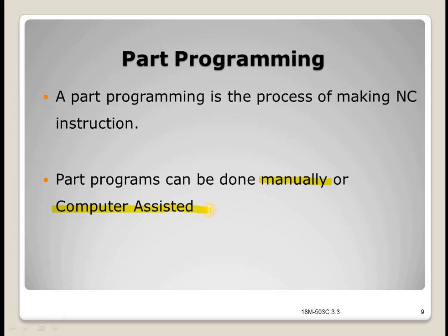So I'll explain about part program once again. The part program is a sequence of instructions which describe the work which has to be done on a part in the form required by the computer under the control of a numerical control computer program. It is the task of preparing a program sheet from a drawing sheet. All data is fed into the numerical control system using a standardized format.